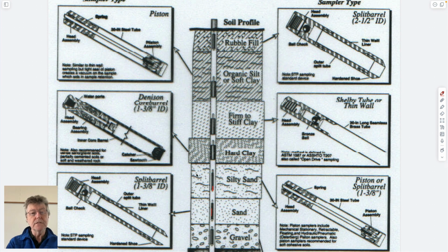And the main difference is that in clays you use what's referred to as a thin wall sampler. So it looks like this. It's maybe a 1/10 of an inch thick wall of a 3-inch diameter brass tube which is coupled onto a coupling that goes down to the bottom of the borehole, and it's pushed in just like a cookie cutter. And as it's pushed in, the soil rises in it. You twist it to break it off at the base, and then you recover it.